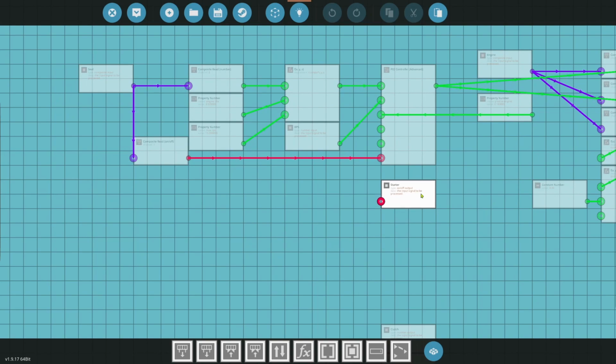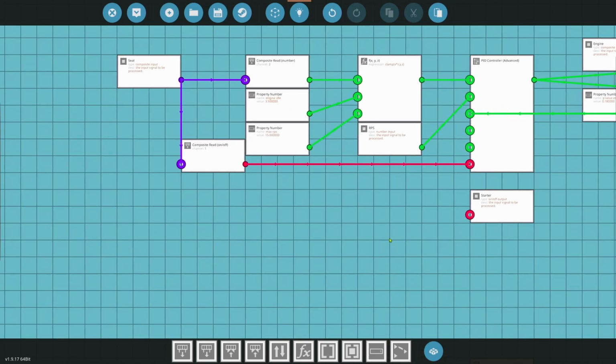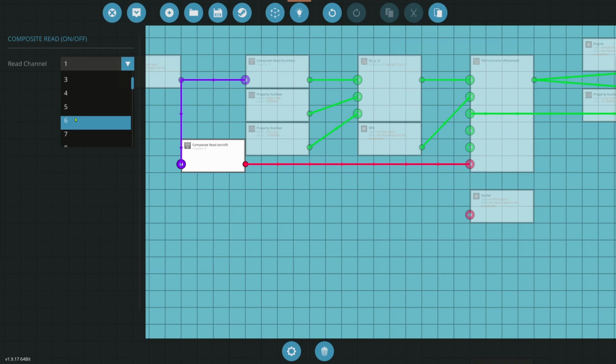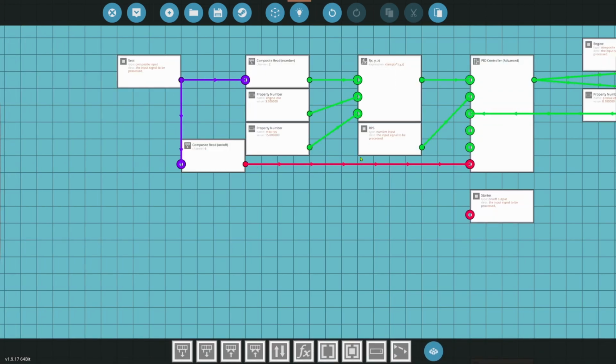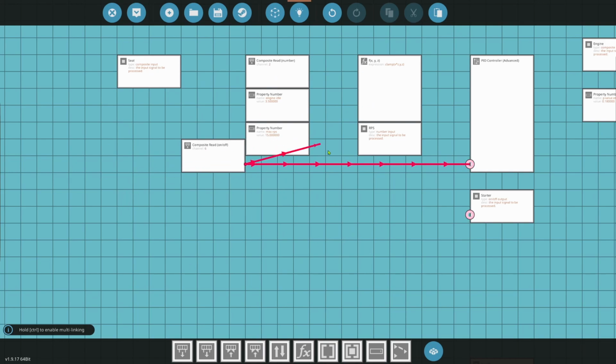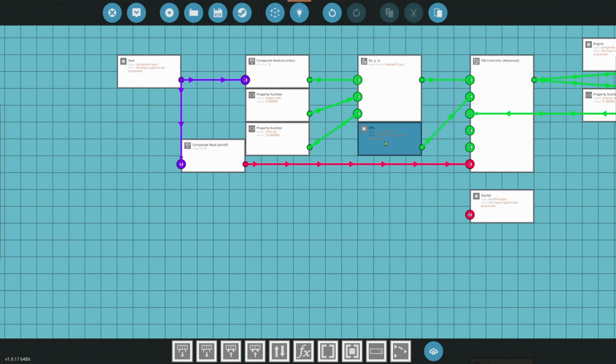All right, so when we want to start our engine, there are 2 conditions we want. I forgot to change this to 6. Again, this should be 6 because that's what we put on our seat. There are 2 conditions we want to have the starter go. One, we want the engine to actually run. So we want 6 to be on, and we want our RPS to be less than, and I usually do 2.5. Once the engine gets above 2, the engine will be self-sufficient and will run. I do 2.5 because that gives me a little bit of extra speed on the engine so that it will not stall right away. It overshoots a little bit and keeps it going.